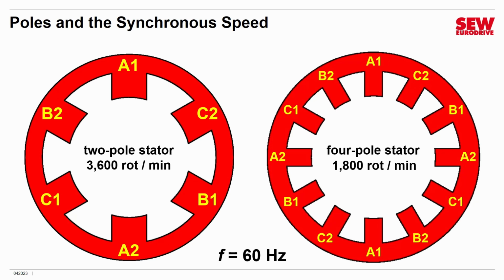And in the days before variable frequency drives, that is how you varied the speed of motors. You used different numbers of poles to achieve different speeds. Variable frequency drives were a real jump forward because they allowed you to have an infinite range of speeds between maximum and 0. Get to that in just a minute.